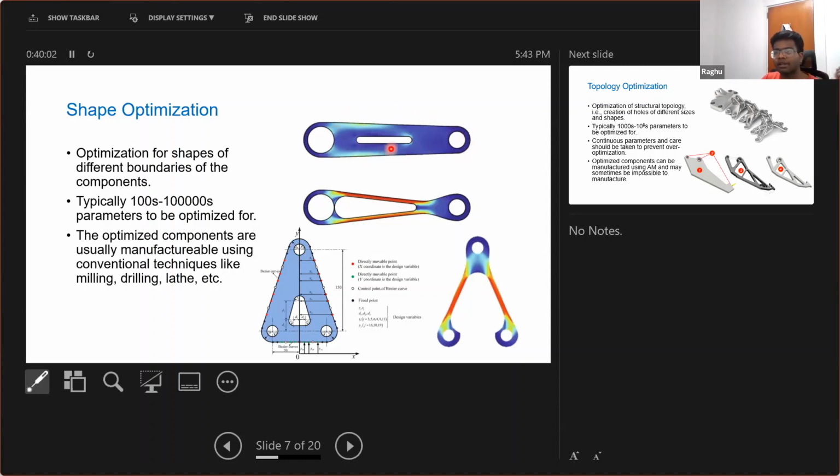Say this thing is 2 kilograms currently, the initial solution. You want to optimize this shape, this slot in between, and these edges here, such that you have weight loss, but you want structural integrity. That means when you are tightening a nut, you don't want the wrench to break. So you put those constraints, and the optimization algorithm would modify this shape and the outside shapes to be something like this. Clearly, visually, this thing is much lighter in weight than the original solution. However, there is still very good structural integrity as per your needs.